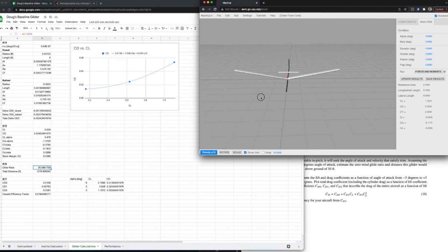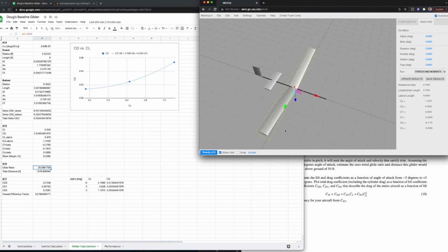So this wing is really not optimized. We've just taken a rectangular wing and just run with it. And you may not want a rectangular wing. In fact, drag is reduced if you have a taper ratio of around 0.5 usually, or if you add some twist in the wing. So we could play with both of those. We could play with some washout in the main wing. We could play with taper ratio, tapering this down, and possibly increase the aspect ratio at the same time.